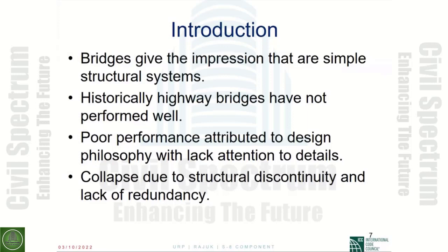We have learned that the collapse was based on the discontinuity of the superstructure and the lack of redundancy of the bridge, because it is unlike a multi-story building. A building is a highly redundant structure, but a bridge does not have as much redundancy as you see in a building.